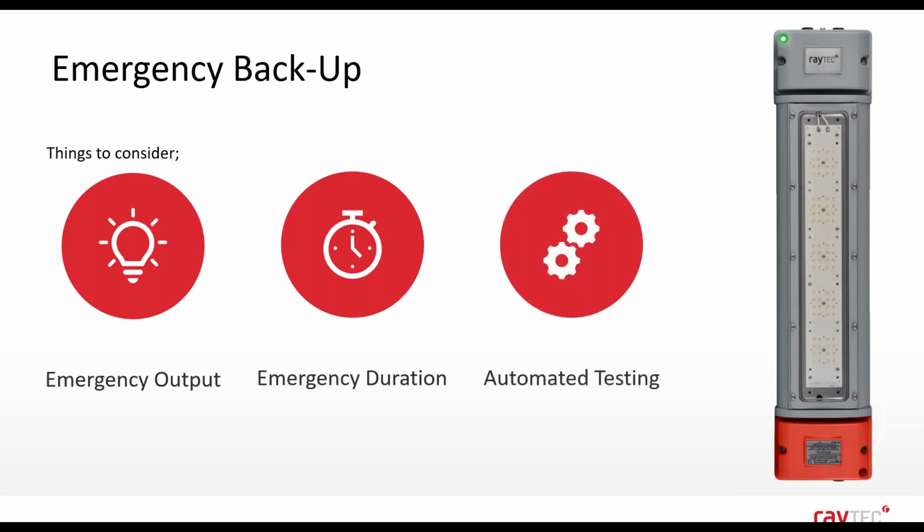And other considerations should be whether the luminaire has an automated testing feature. Without it, someone on site is going to have to manually kill the power to test and to ensure the emergency fittings are working correctly.